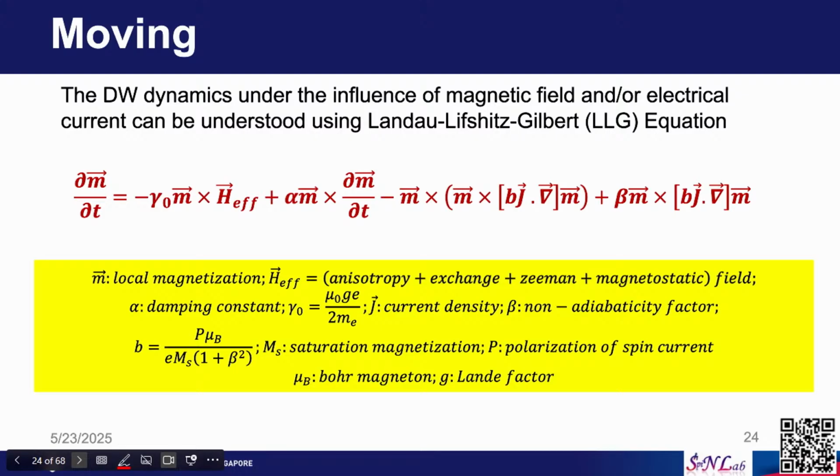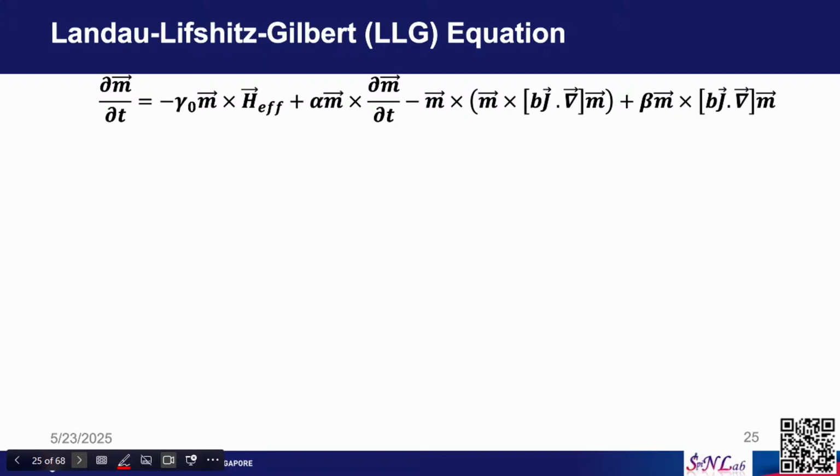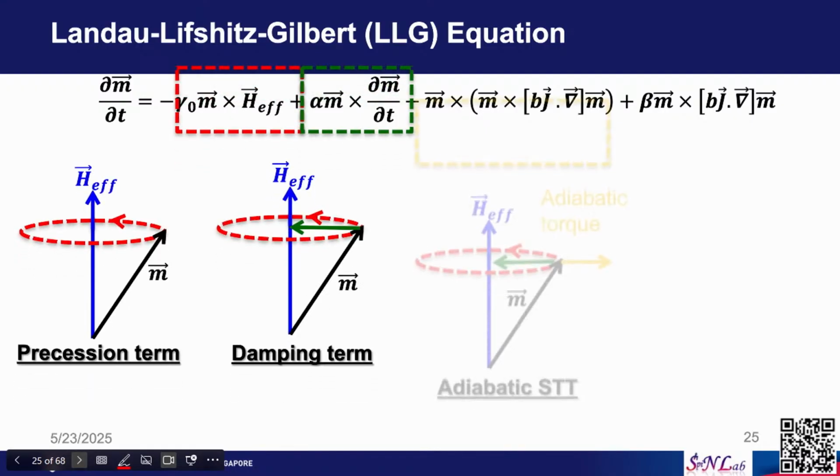Okay, so you can understand the spin transfer mechanism by looking at the LLG terms. So, this is the Landau-Lifshitz-Gilbert term. Then current induced domain wall motion is in this term and here. You do not need to worry too much about this theory, but if you want to simulate the domain wall motion, you can take an equation like this and you can simulate the motion of domain walls. I think we can skip these slides.